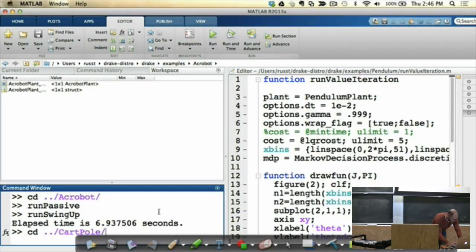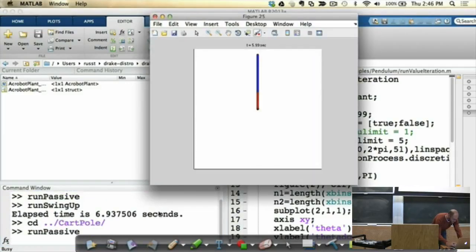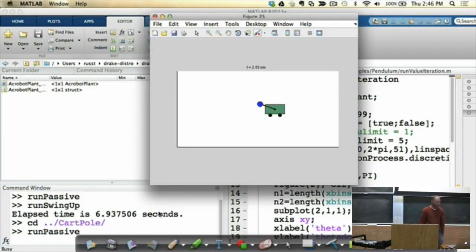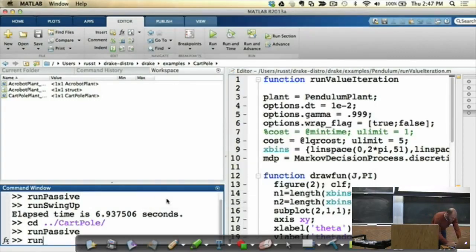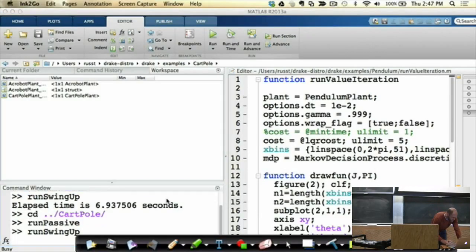All right, so if you just drop it from a random initial condition, you can see that this was passive, so the torque was 0, and you can see, of course, there's an inertial coupling between the moving pendulum and the cart, and we're going to exploit that in the other direction in order to move the cart in order to swing the pendulum. And our goal is to swing this one up to the top.